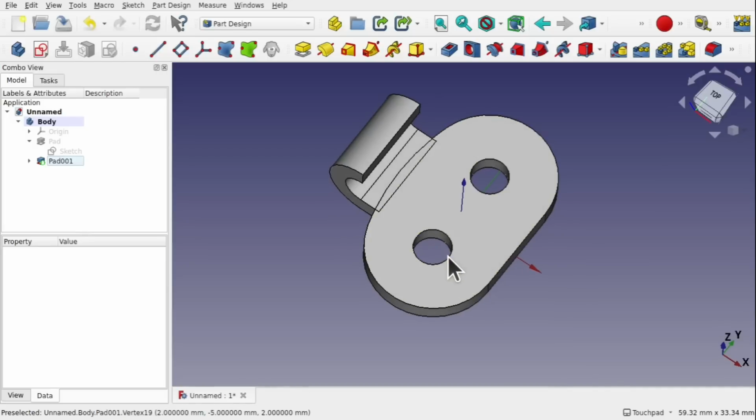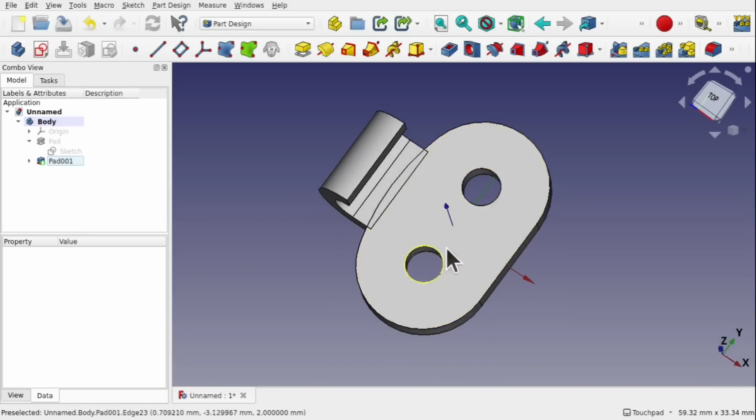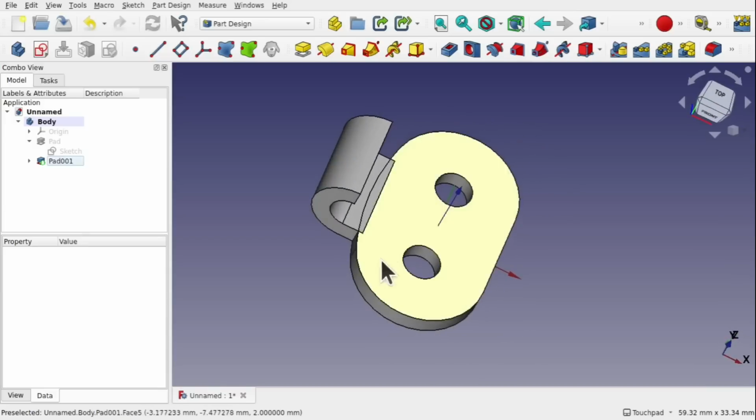Reason being, if you add it earlier on in the process, then we create more faces and more edges, which can break our geometry. So we actually reference it in edges. We don't want to reference in fillets or chamfers because we can add a chamfer in here, and often we adjust those so we can make them 1mm, 2mm, depending on how we want the object to look. If we keep on changing those, we can affect an edge that's referenced to, because we may end up creating a chamfer that creates another edge or another face, and that can be damaging to the geometry that's referenced upon